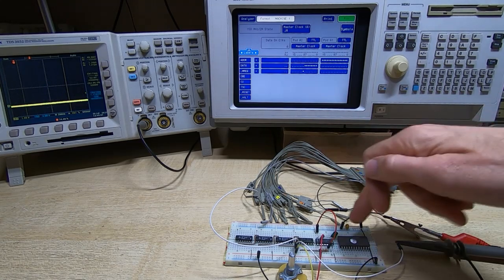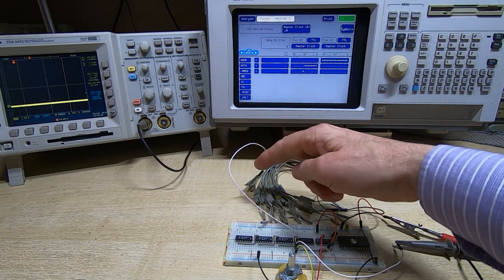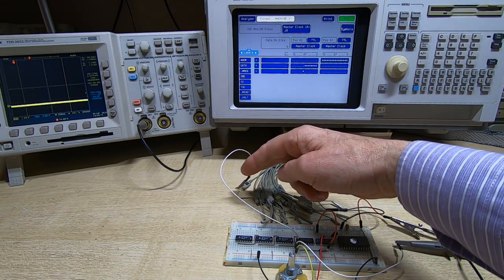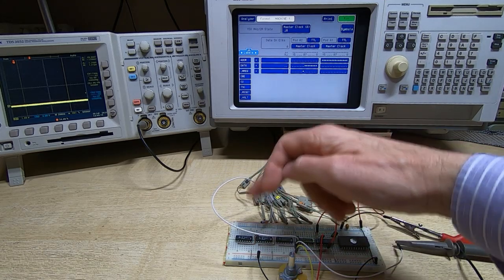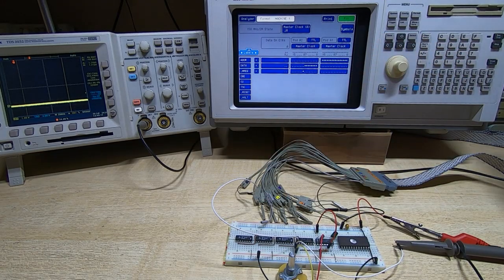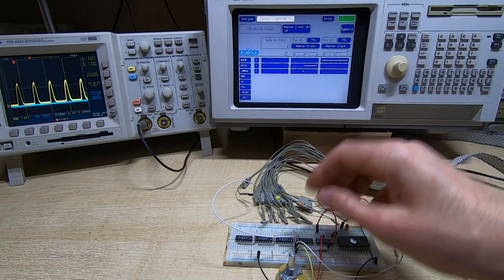So what I've got set up here is the clock is going to our bit 0 input on pod 1, and when we feed this in, you'll see the level start to toggle. So I'll turn it back on and you'll see the arrows reappear. But what I can do is adjust this input level using the pot.